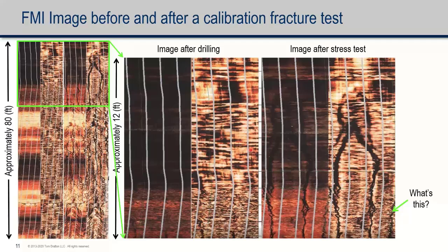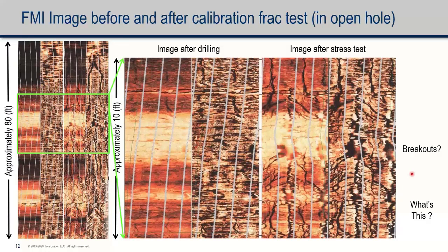And you can clearly see that there's been some change in the image. You've got this classical, I would call it, hydraulic fracture that you see. It is interesting down here. There seems to be like a third hydraulic fracture, which is kind of hard to explain initially. If we scroll down and look a little bit deeper, this really surprised me when I saw this. What appears here appears to be like breakouts. And there's a lot of damage on all 4 sides of the borehole.